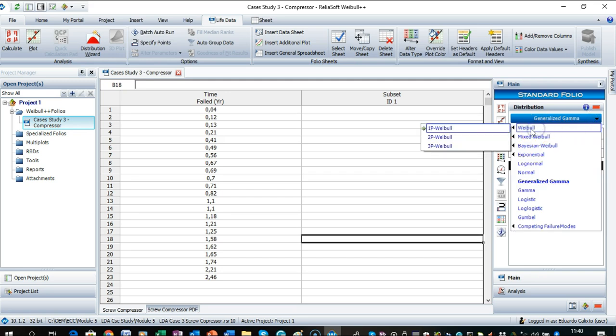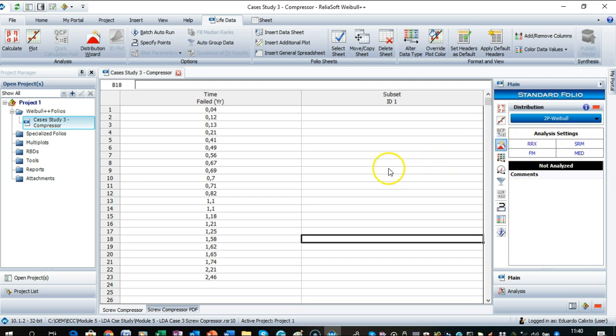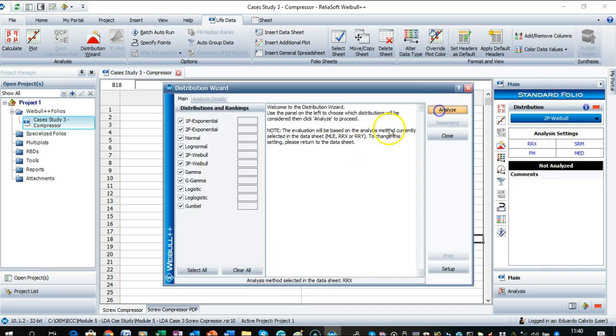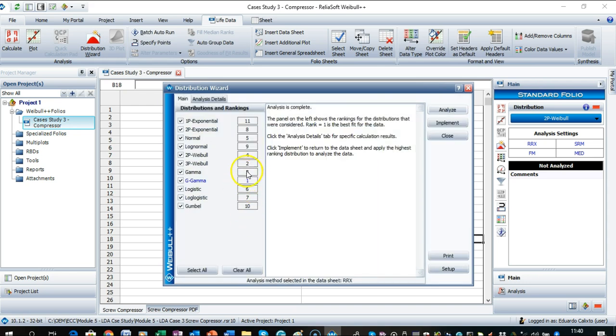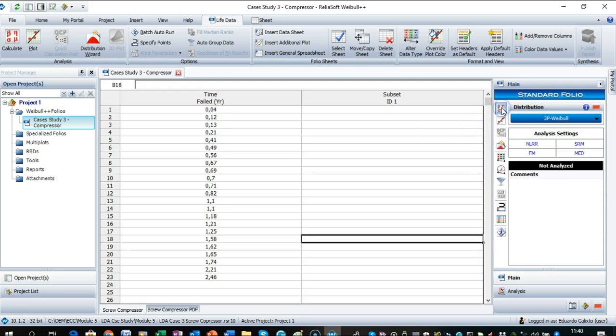So the software does not approximate for. Now we have rank regression just to check the second option. The second one is Weibull three parameters. So let's take a look at the Weibull three parameters. That's the result that we've got. So again, Weibull three parameters, they just use the nonlinear regression because of the three parameters. And here we have the issue that we have a negative gamma.